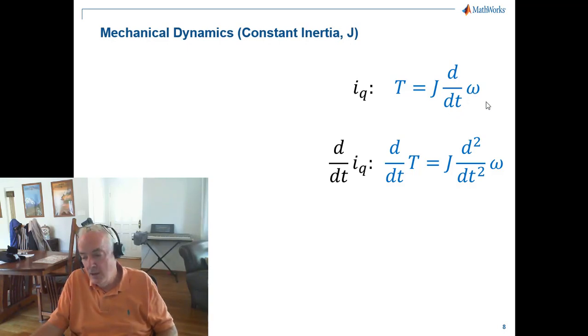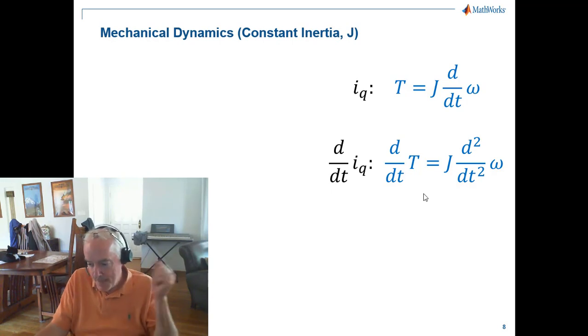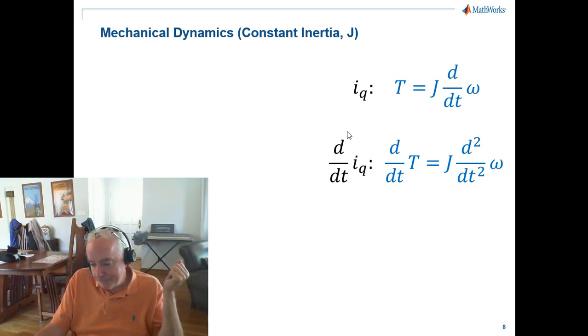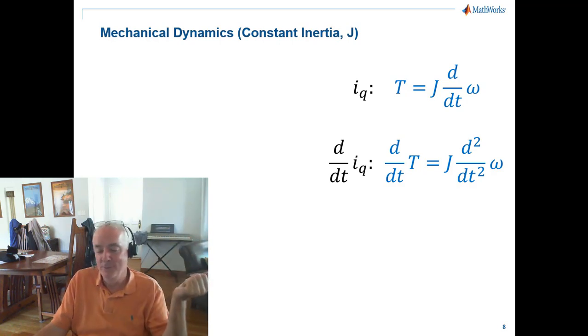Hence, we know that the acceleration will be finite, because it is the first derivative of the angular velocity. Now, because we do have some di/dt terms for quadrature, it needs to be even a little bit smoother than that, meaning the next derivative up, the one beyond acceleration, which is called the jerk, needs to be finite as well.